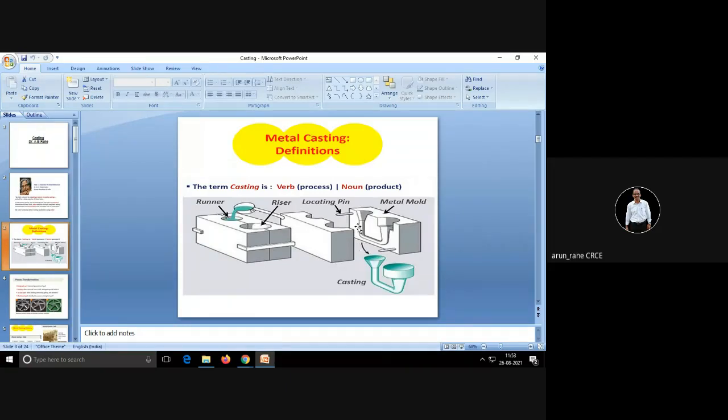In the manufacturing process, what we do is first we make these two blocks, plain rectangular blocks, then we drill and ream two holes for the locating pins, and then with reference to these two locating pins we cut this shape separately. Like I have drilled and reamed these two holes. Now with this reference I will do machining of this shape. Again with these two references I will do machining over this.